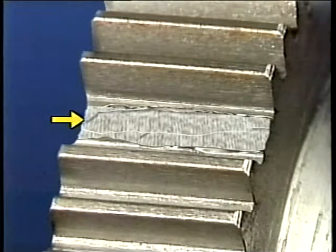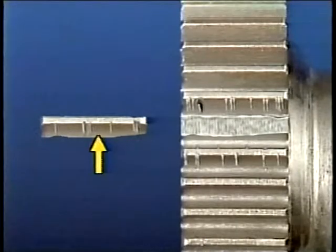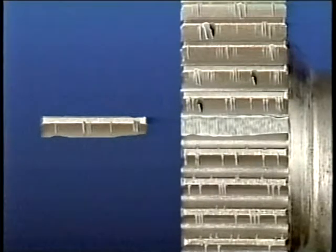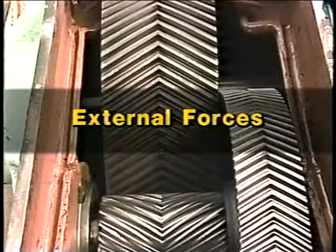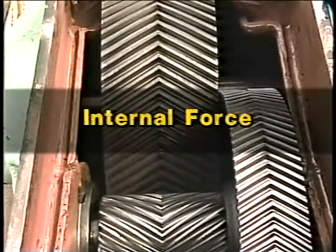The appearance of a break that has been caused by overload can be described as being rough. In addition, the gear tooth broken by overloading and the adjoining gear teeth may be deformed. And in some cases of overloading, all of the teeth on a gear may be deformed. An overload which causes a break may have been caused by forces external to the gear set, or it may have resulted from an internal force.